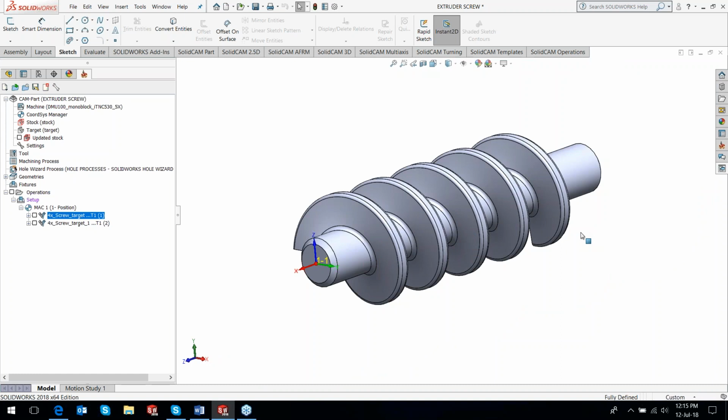Now, imagine the same part given to you, and you're going to work on it using our generic 4 and 5 axis engine. The calculation would be pretty quick. It would probably take a minute. But to get to that minute, the amount of work that you need to do would probably be an hour or two before you get the right result. But here it's simply like doing a 3-axis machining. Select a part and hit the calculate button, and it will do the calculation for you.